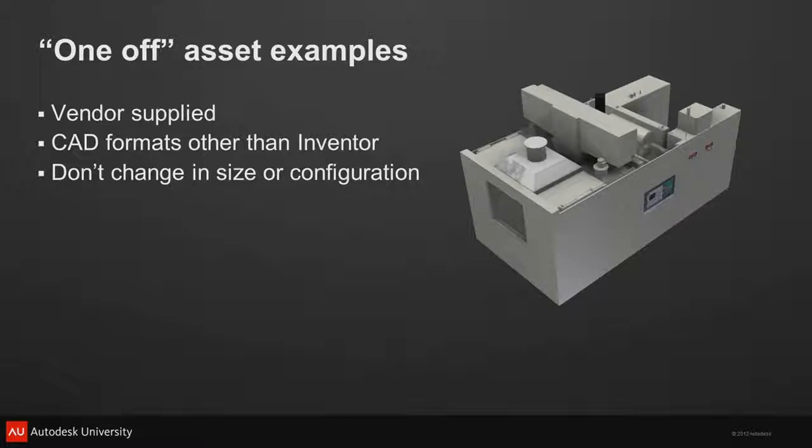And what better place to shrink wrap or gut something than the original tool that was used to create it, right? If it was made in Pro-E, use Pro-E to go ahead. Use their shrink wrap tools. Have them get rid of all the guts inside and just give you the outside shell, okay? Now, Inventor does have tools that allow us to be able to do this. But again, the best tools to do that are the native application where they came from.